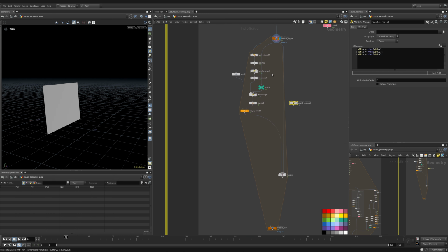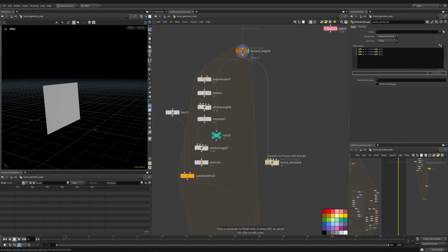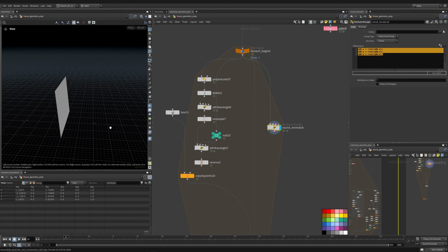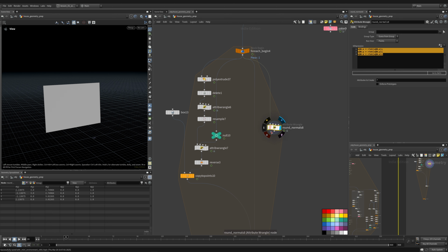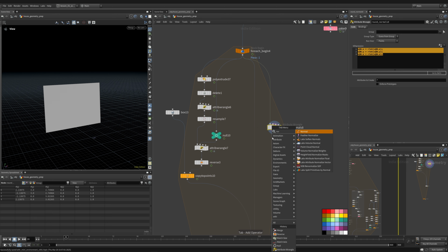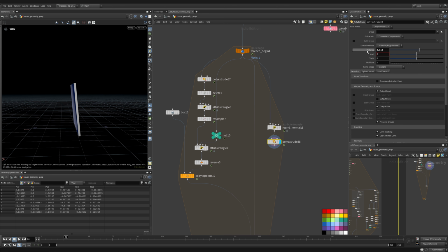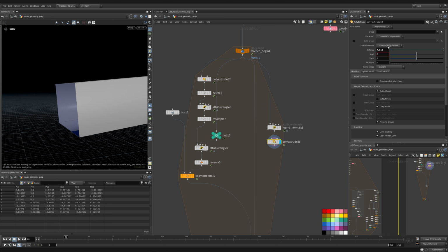And if you remember from the last lesson, what this did was it took our geometry and rounded the point normals to the nearest integer, which essentially snapped them to move either in full Z, full X, or full negative Z or negative X. And now if I do a poly extrude, it won't use that yet, but what I can do is set extrusion mode to point normal and from pre-compute to existing.